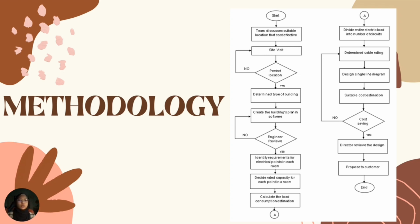Okay, and then we create the building plan, and we submit it to our engineer to do some review. If the engineer rejects it, we have to create another floor building plan. If yes, we need to identify the requirement for the electrical points in each room, and we decide the rated capacity for each point in a room. We also need to calculate the load consumption estimation. Also, we have to divide the entire electric load into a number of circuits. Okay, so after that, we have to determine the cable rating that we are using in this project.